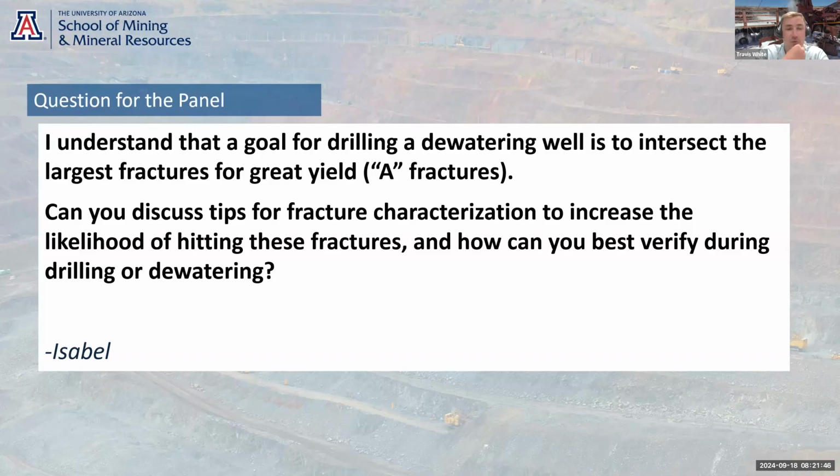We've had cases where we've moved holes a couple of meters, and they've been dry. So it's really important that you drill that pilot hole and you understand the orientation of the structure that you've hit with the pilot hole, so that when you drill the production well, you move it along strike with the structure that you've hit.